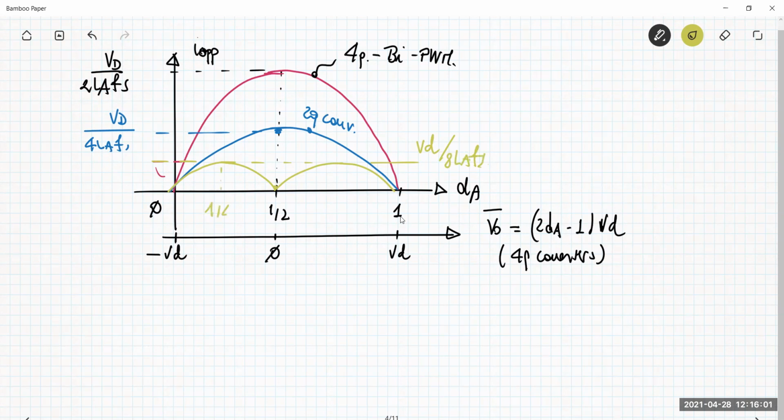It's for 1/4, and this is 3/4. This is obtained 1/4 when the voltage is negative, and 3/4 when the voltage is positive. So here you can see immediately that the effect of having a switching frequency is just to reduce the residual ripple in the output current due to the switching action, as I said before.